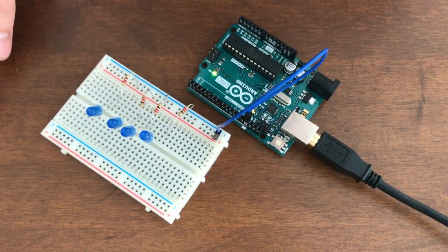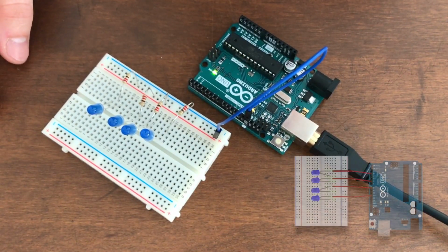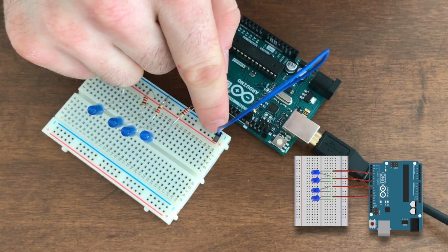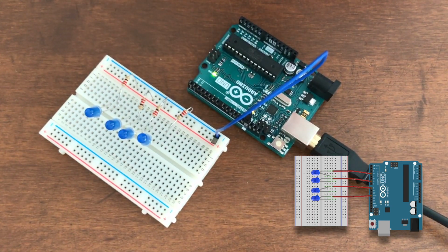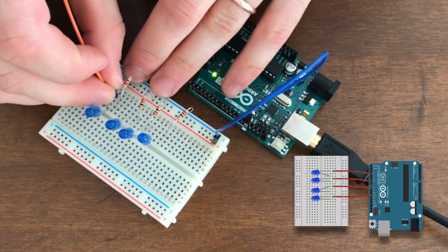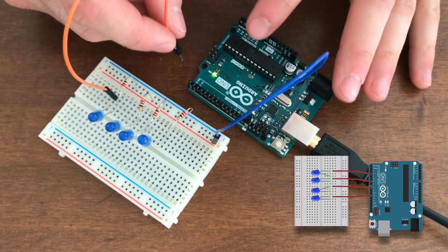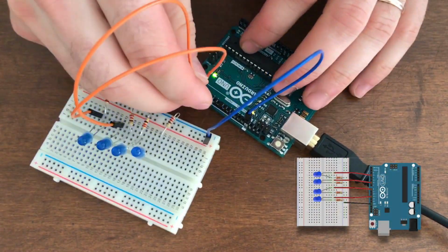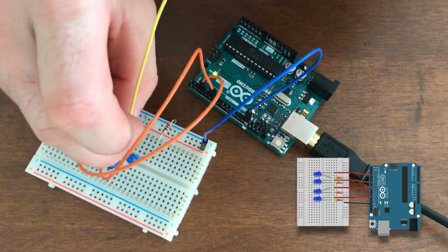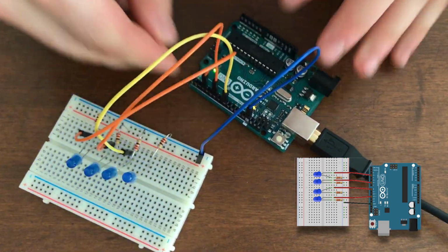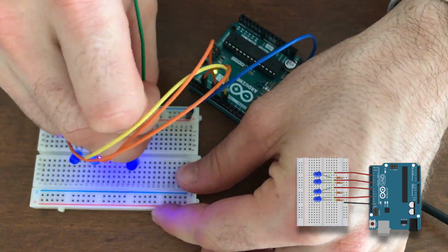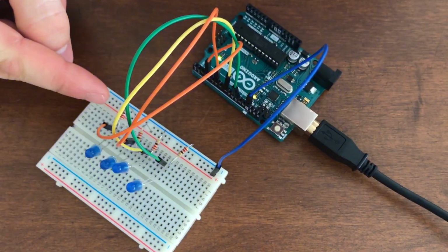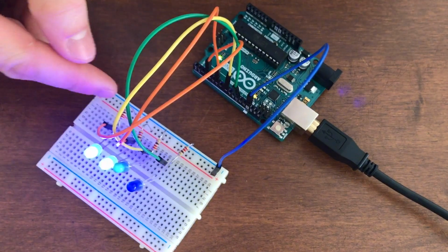All right, to make the Arduino run multiple programs, I've set up 4 LEDs with resistors running to the power rail, and then a jumper wire running to ground on the Arduino. From there, all we need is 4 different pins, and this specific one I'm running from the anode on pins 3, 6, 8, and 11. What we've got is 4 different pins, 4 different circuits, all running to the ground.